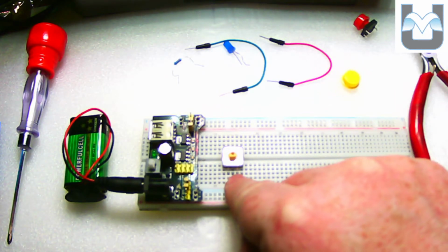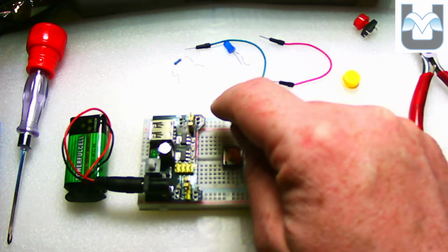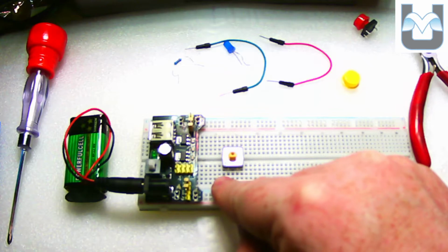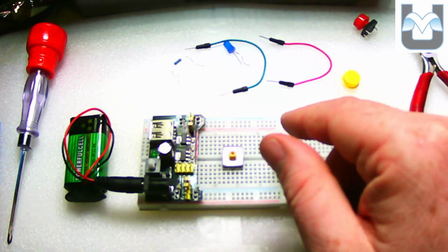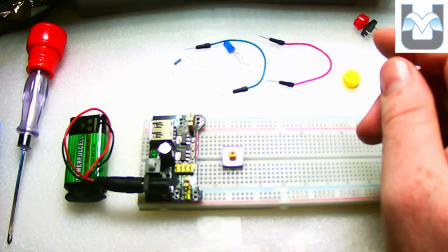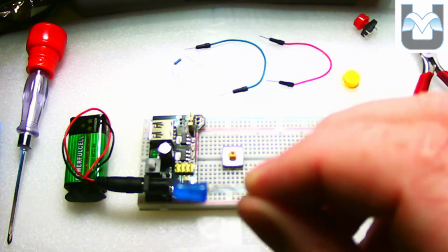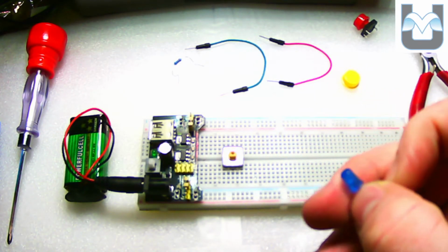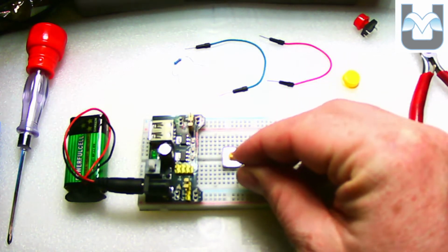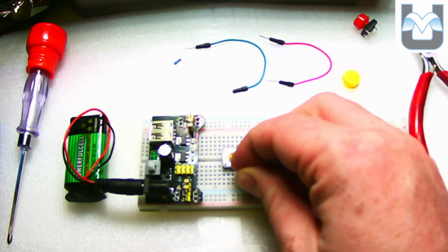Notice that I've got legs that have one space of gap in between them on both sides. And I know that on my left here I have the 1A and on the right I have the 2A and B for that matter. Let's take our LED and hook it up. I'm just going to take a quick look to find where the flat side is. And the flat side is on that side right there. So I'm going to go ahead and hook the LED in here.